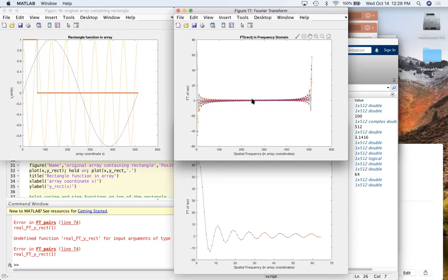And then we see the replicant here, the aliased replicant with its peak at 1 over the delta X, and our delta X here is 1 over 512, right? And so that's where it happens, at 512. So it's sort of like, okay, I think I get what you're saying. Yeah. So as you get closer to that frequency, which is just the amount of data points, you're still going to get some sort of artifact there.